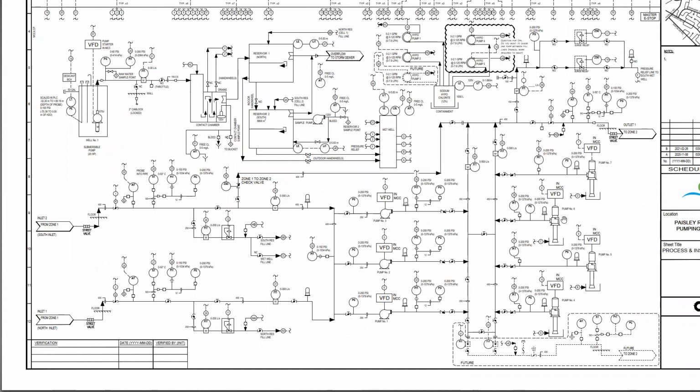So these pumps are mounted vertically in the building, and they have a shaft that runs down into the reservoirs, and then we'll draw water out of the reservoirs, and we can push that water into the zone. So at night, when usage is low, we'll pump and we'll fill the reservoir so that in the morning we can use the water from zone 1, but also add the water we've stored overnight into that zone. So that's the main water flow process.